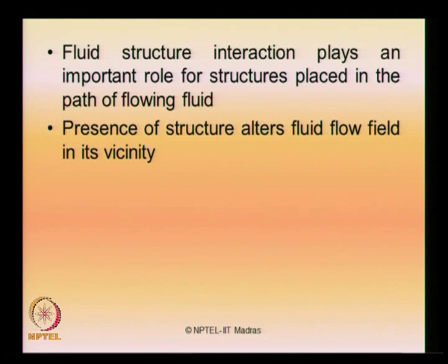Essentially, if you look at the fundamental aspect of influence of the structures in fluid flow, it alters the flow field near its vicinity, that is very important. So there is a far field disturbance, near field disturbance. So essentially we are focusing on the near field disturbance, that is what is the influence of the structure on the fluid flow characteristics in its vicinity.